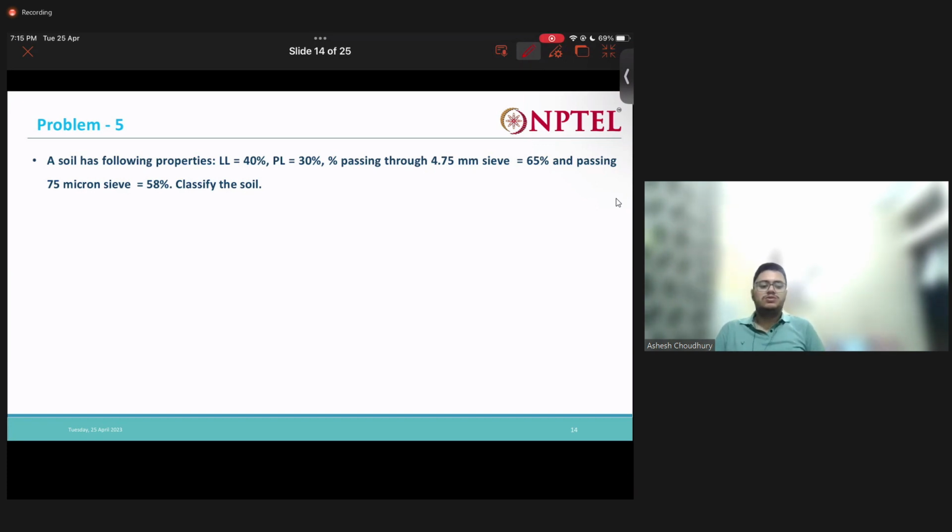What we need to do is the dry sieve first, and if there is a considerable amount of clay fraction, then we need to do the wet sieve analysis too, followed by our hydrometer analysis, right? After doing this analysis, we can draw our grain size distribution chart. From the chart, we will get an understanding of the grain size, what fraction of grain sizes are present in the amount of soil that we have tested.